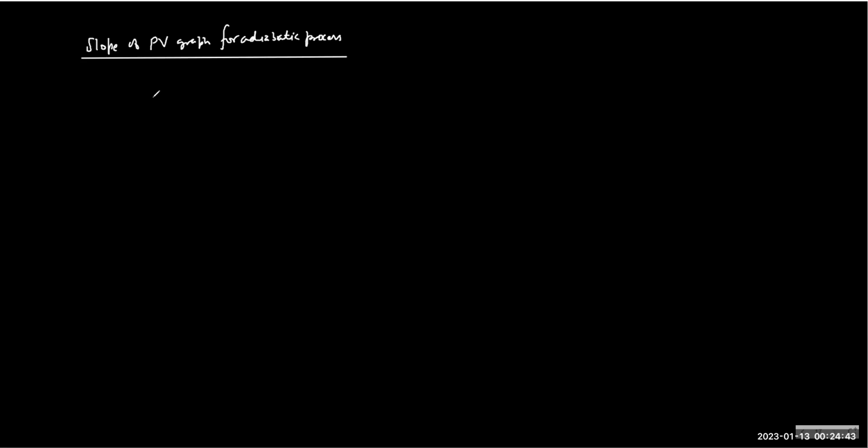So now we know dP by P plus gamma dV by V is 0. So if you find dP by dV, what you get? Minus gamma P by V. Earlier it was minus P by V for which process? Isothermal, right? But now gamma has come here.